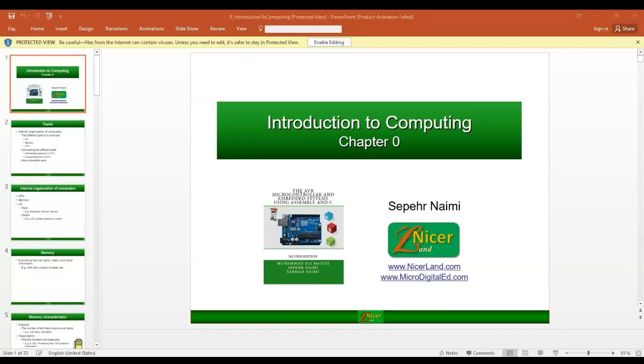So this 5 is given to the data bus and placed at position A. Our PC counts one more, and at point 3, 81 in hexadecimal is written here. The instruction decoder checks the corresponding functionality, and using the ALU, A plus B would be performed.